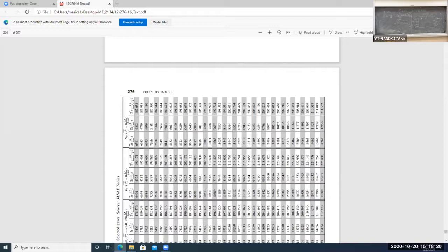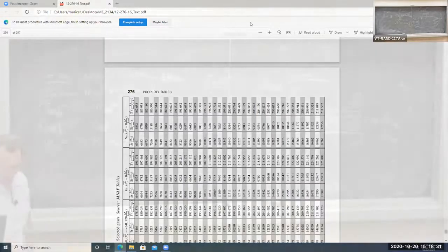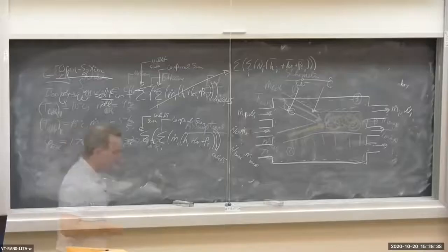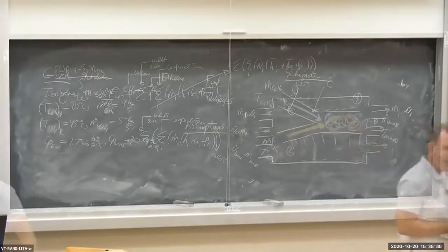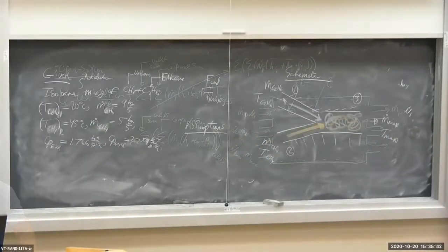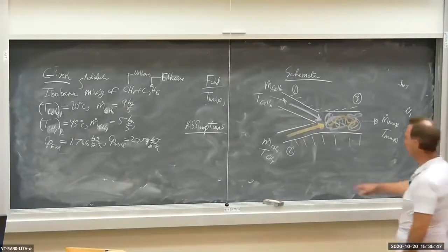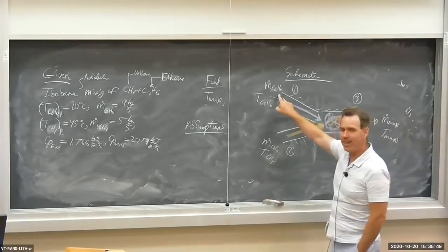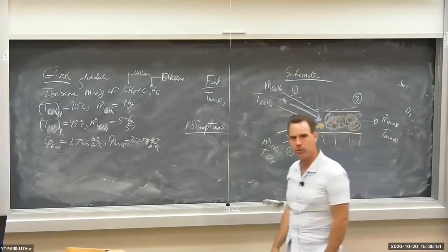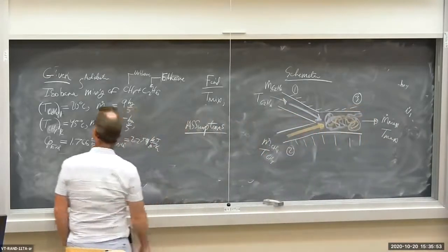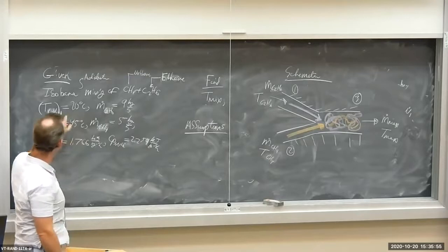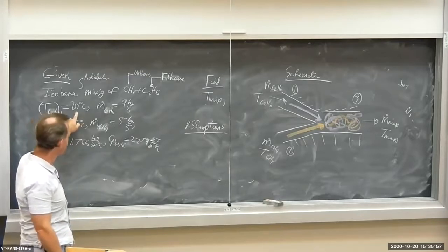Okay, let's take a break for a second and we'll do an example involving an energy balance on an open system so that we are all pretty clear what to do. So let's do a problem here. We have an adiabatic isobaric mixing chamber that you see right here. At inlet port number 1, we have ethane, C2H6, flowing in at a temperature of 20 degrees C.